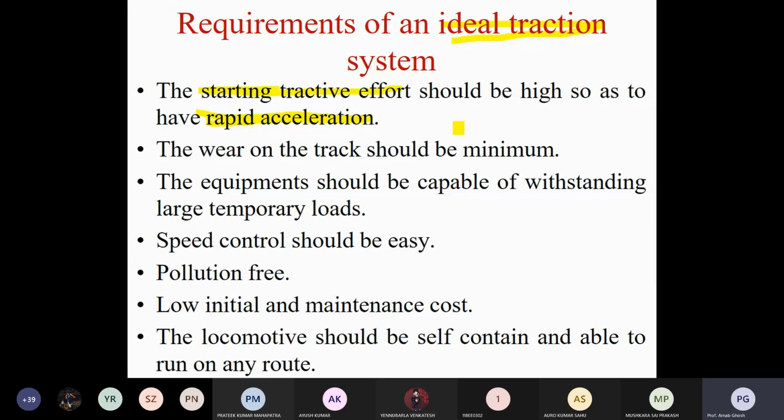So rapid acceleration depends upon your converter. That means a power electronics converter is used as the controlling unit in the drives. Now, the motor behaves like a load. The supply of the motor comes from the power supply, the overhead connections. In between the power supply and the motor connections, the power is processed through the power electronics drives. So the power processing unit is also very important.